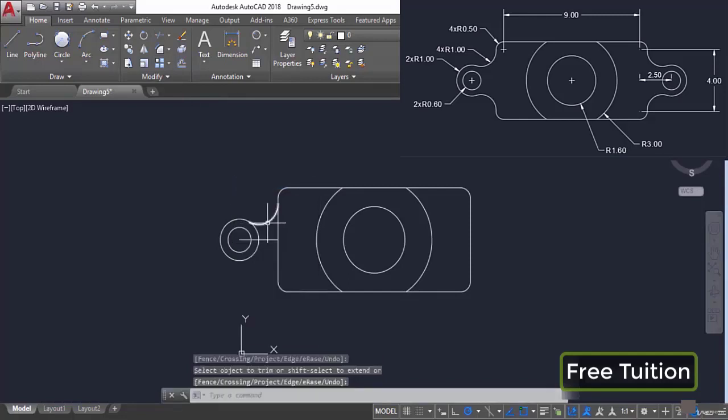Now we can make a mirror image. So I'll go to mirror, select this portion, press enter, click on this midpoint and click on the center, press enter again. So now we don't need this part. Also we don't need this portion. So I'll go to the trim tool, press enter and remove this portion.